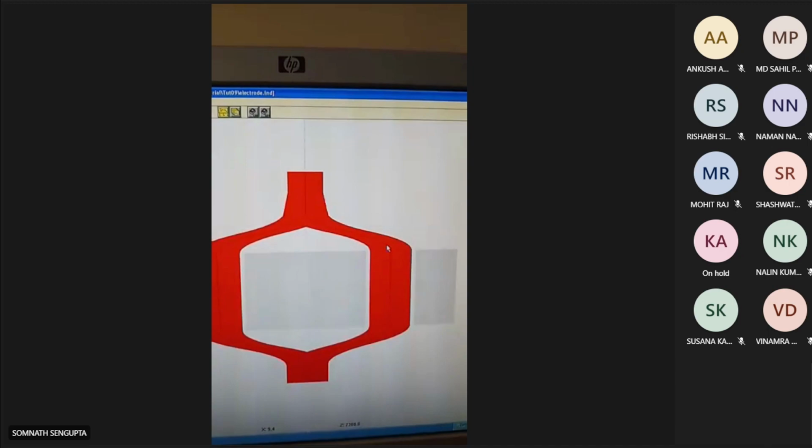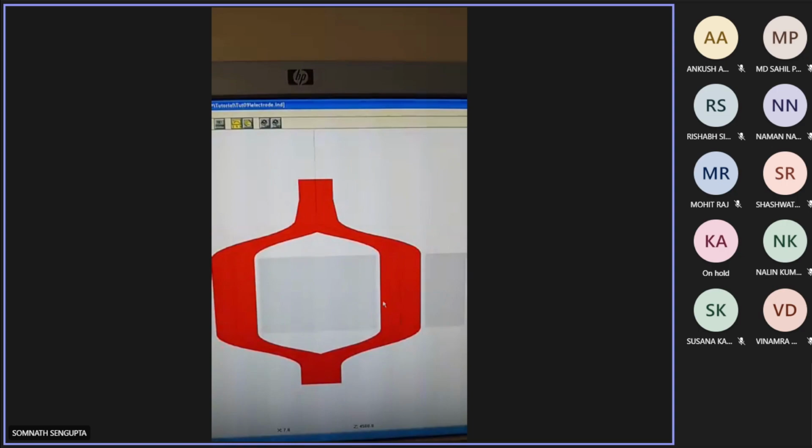It may be used as an optical fiber sensor also. This is a very highly sensitive sensor, and in place of the waveguide or lithium niobate crystal, optical fiber is used. Their principle is the same. If you apply some force, the refractive index changes in one arm, causing a phase change of light in that arm.